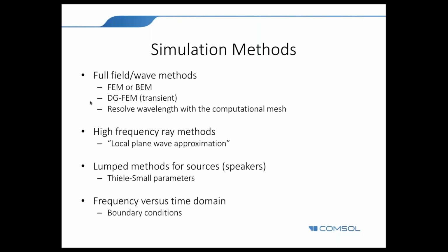From the boundary condition perspective, you can use simple normal acceleration boundary conditions, or you can use lumped methods and sources to place speakers inside your car cabin. And you can use frequency domain solvers, or you can go to the time domain to get simulation results there.